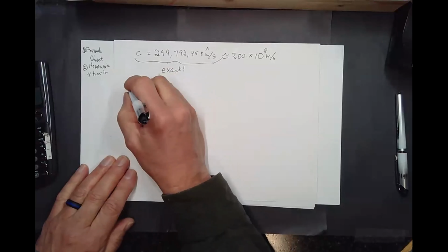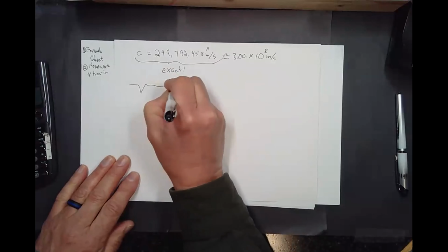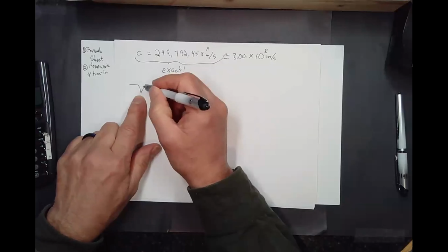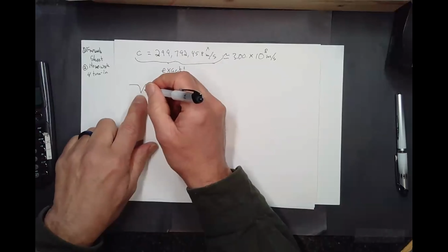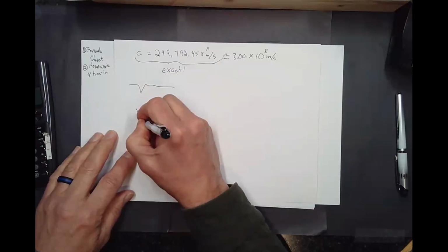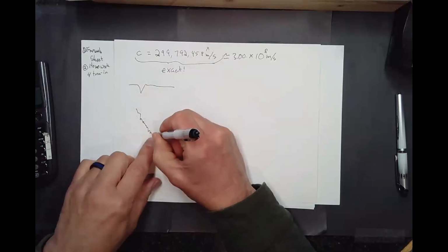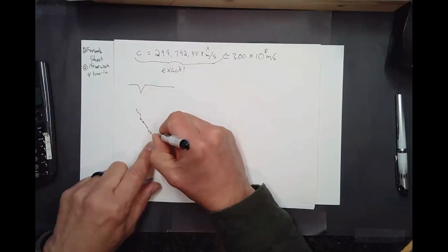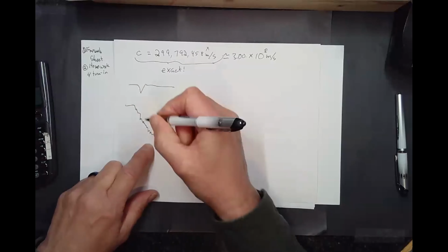Here's the problem. If you've got a couple of what you think of as nice little scratches in there, maybe you made them triangular shape, and you look at this thing under an electron microscope, the sides of the V as you're going down are kind of bumpy, as is the bottom of the V. So that's what it might look like.